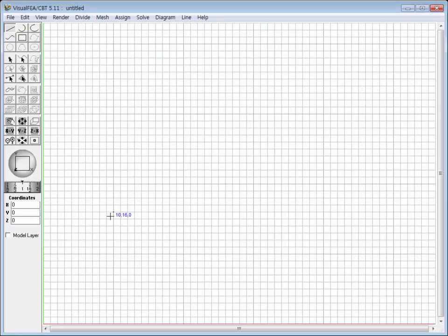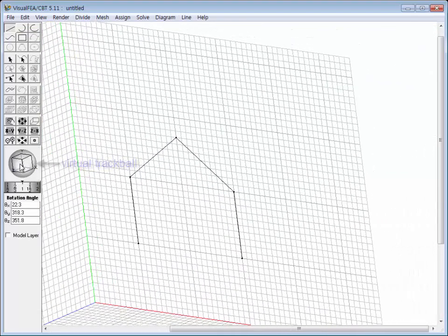The modeling may be started from a few frame members, created simply by drawing straight lines. Each of the lines represents a structural member, with 2 end nodes. The view can be rotated easily by using the virtual trackball. The modeling space can be better visualized with the three-dimensional grid.